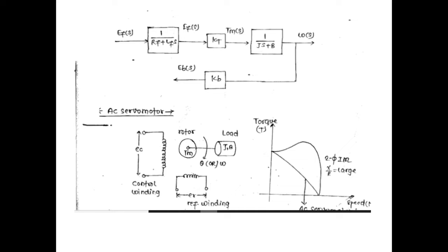This difference of position or difference of angle is a physical quantity. It has to be converted into something which could control. So I convert the difference of position or difference of angle into an electrical quantity. Now, which transducer is helpful for me to do so? Obviously, I will have two types of transducer. One is a potentiometric error detector, another is a synchro, which I am going to discuss after this slide.